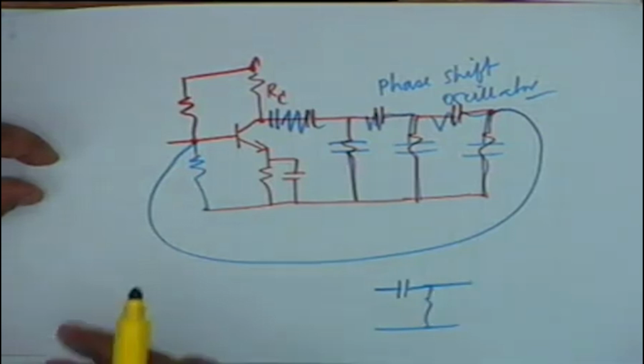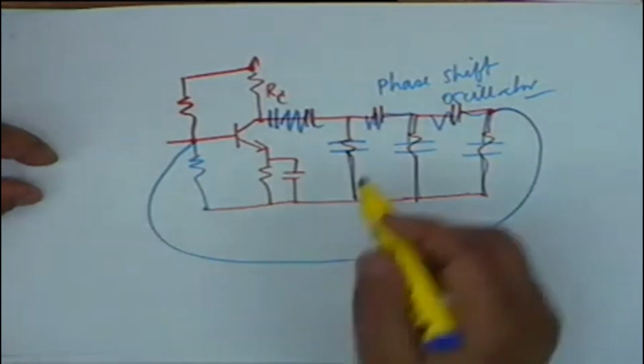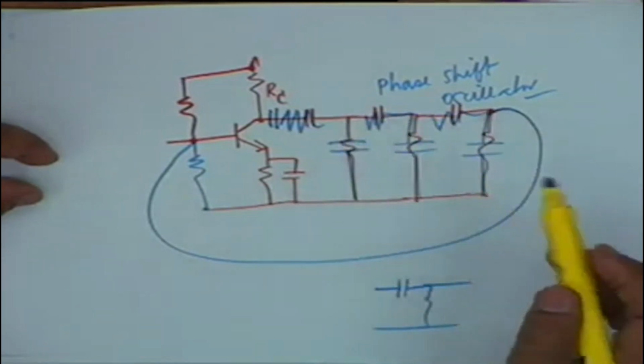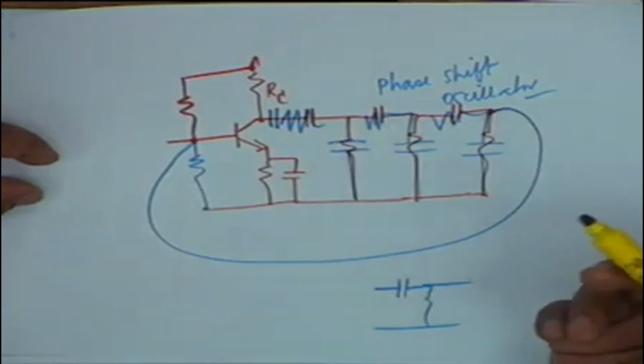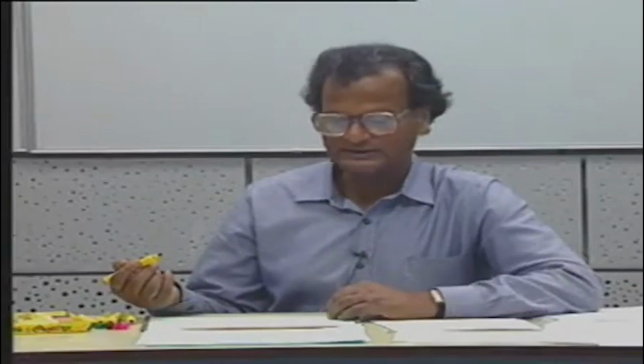On the other hand, if it is an RC circuit, the output shall lag the input, and therefore if we take RC, RC, RC, it shall be minus pi. Agreed? Plus pi or minus pi, it does not matter, either way it shall work. But the problem is how to analyze this circuit. What is the frequency of oscillation? Because the amplifier is not ideal.